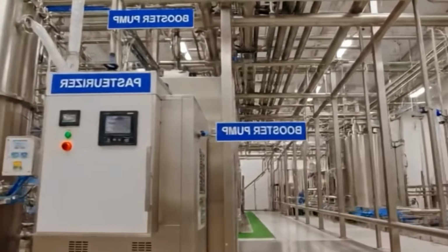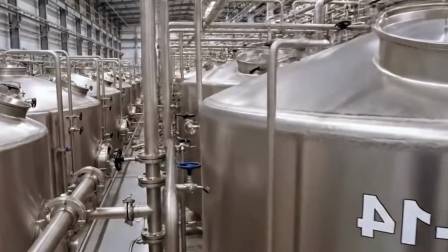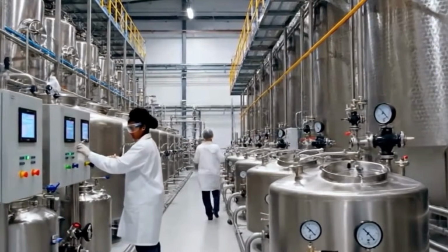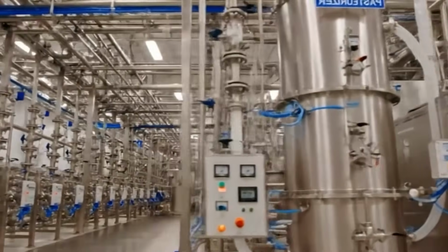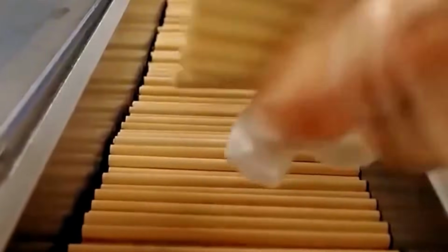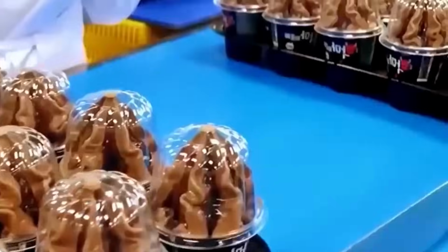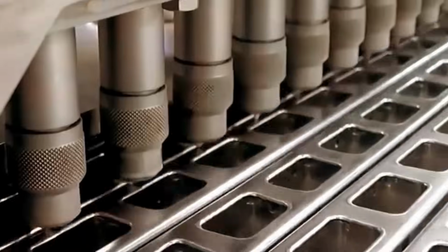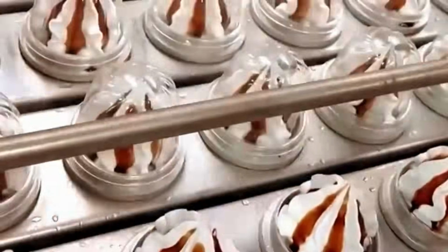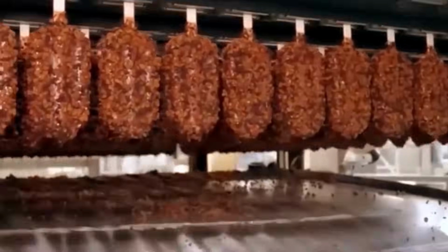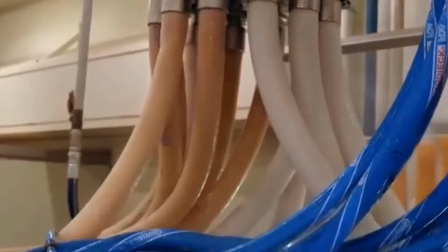Milk fat content is measured using inline infrared sensors to meet formulation targets, typically between 8 and 12% depending on the product specification. Sweeteners such as granulated sugar or glucose syrup are stored in dry bins or heated tanks. Sugar is conveyed using auger screw feeders into blending tanks, while glucose syrup is pumped through jacketed pipelines at a regulated temperature between 45 and 60 degrees Celsius to maintain viscosity.